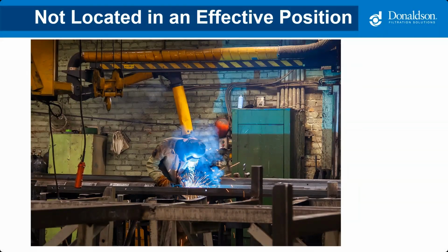We have other options. We've done some really good source capture of weld fume with specialty-made MIG guns that have the fume extraction built into the gun itself, and then we run a high static pressure system of multiple welders back to a single collector. Those are extremely effective. Again, the welder sometimes complains because now they have to use a different weld gun, and they might say it's bulkier or heavier until they get used to it.